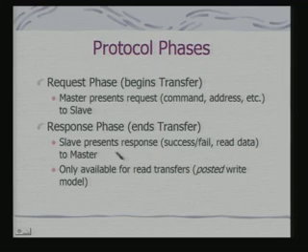So, the slave presents a response in the response phase, success or fail. So, it's only available for read transfers, in the sense of the posted write model, that is, you have posted the request and then you will be doing it later on. So, a kind of response phase tells you whether it is a success or failure, and it can even be done later on.